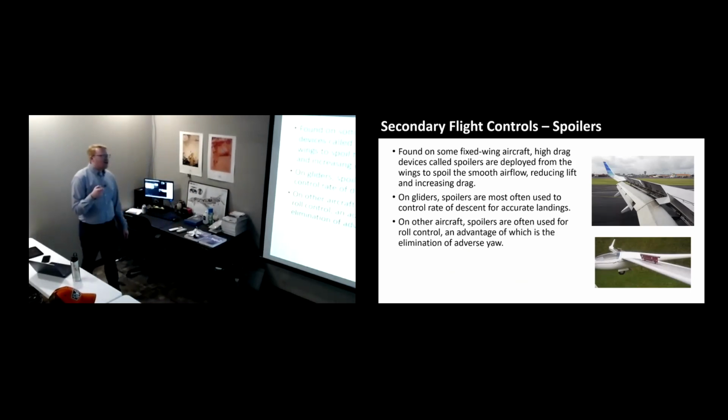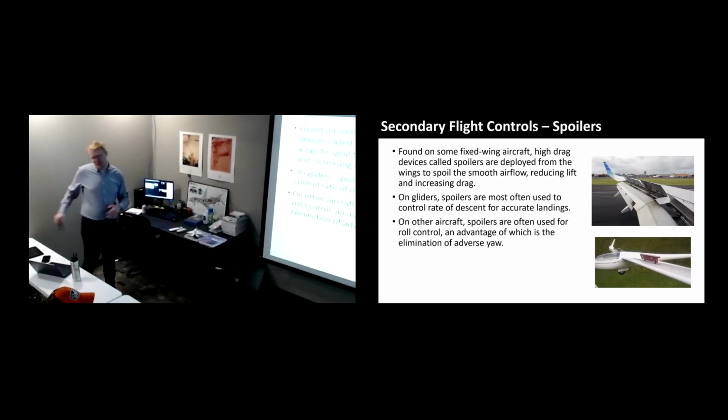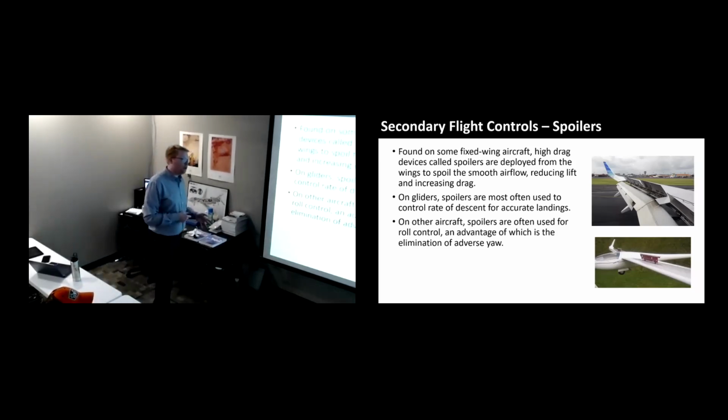Okay. Spoilers. These have one big purpose. These are high drag devices. So we've been talking about how to produce as much lift as we can, while minimizing as much drag as we can and dealing with its effects. Now, these are times we want to produce a lot of drag.